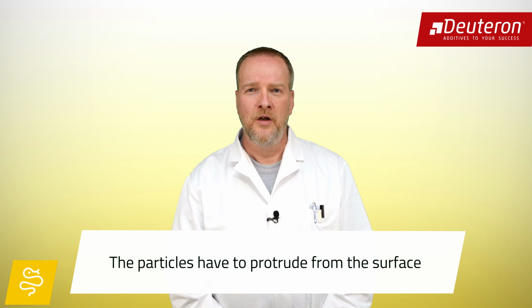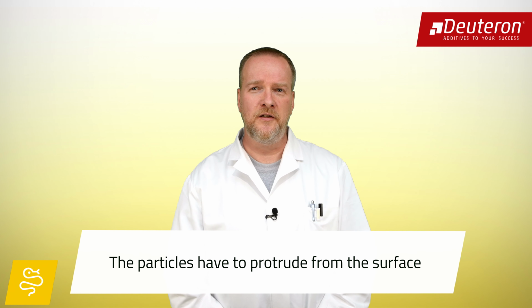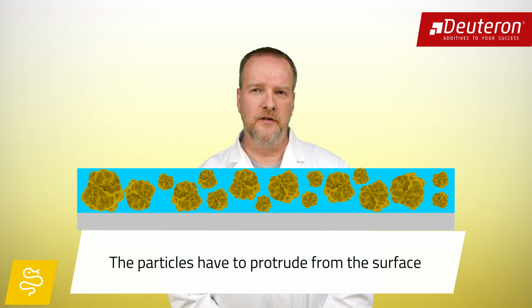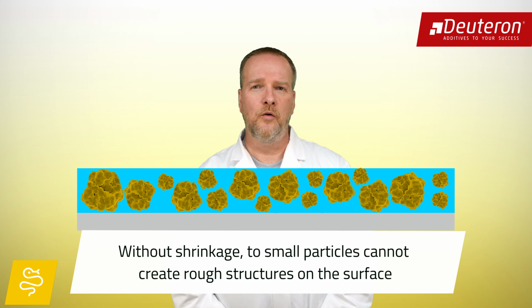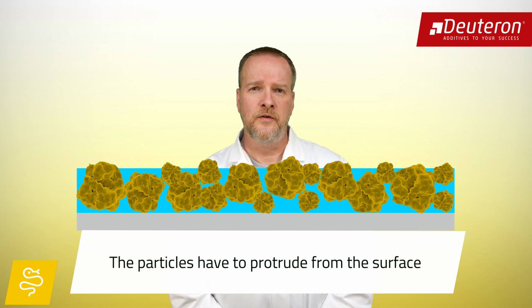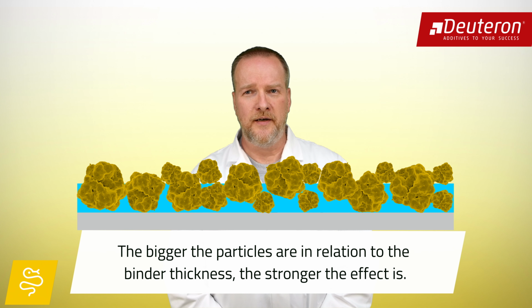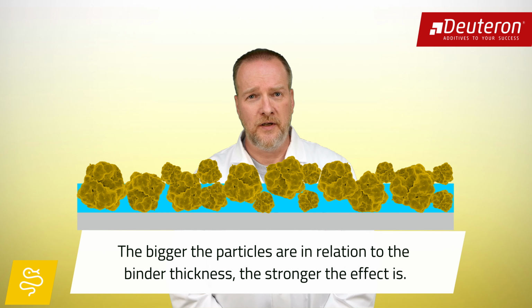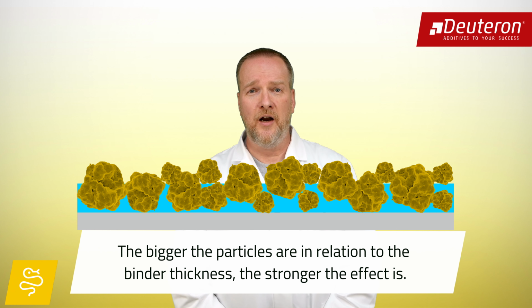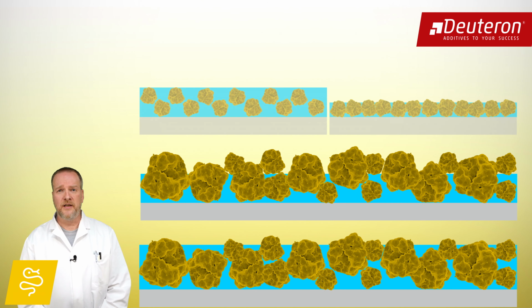In case of applications with less or no shrinkage during the hardening process, particle sizes nearly or more like the layer thickness are required. If the layer thickness is too high for the particles, no effect is possible. Bigger particles will lead to coarser structures in the surface. The effect is stronger the lower the layer thickness of the solid binder is. Of course, this also happens in the respective ratio with other particle sizes. If these dependencies are considered, very wide ranges of effects can be created, for example in combinations.